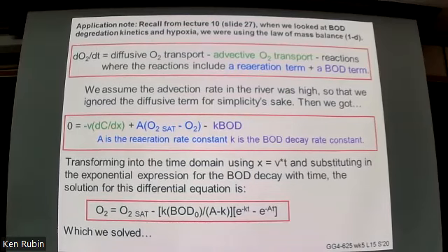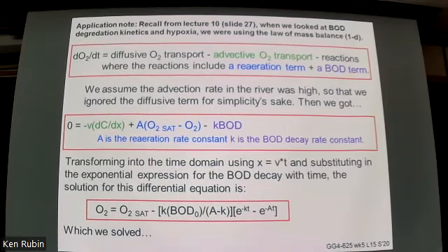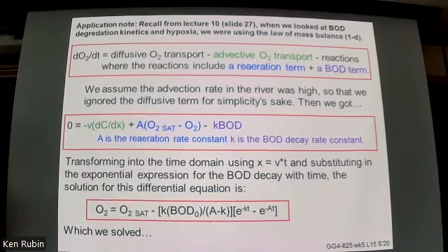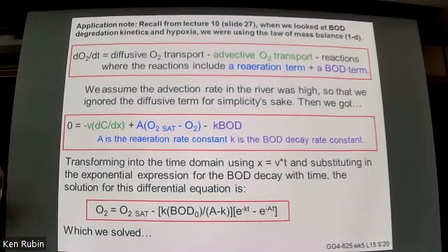The reaction terms, which we've already talked about, are internalized to our control volume. They have to do with phenomena, whether they're chemical or biological or radiological, that are happening within our volume. Whereas this term is more related to, this is the advection term, obviously, how fast is the water flowing by compared to the rate at which the input of contaminant is.